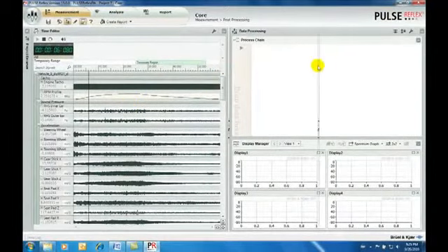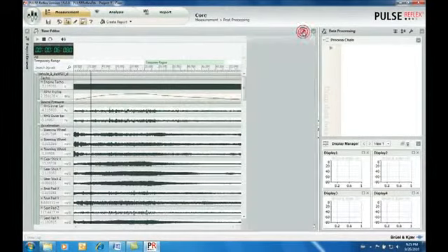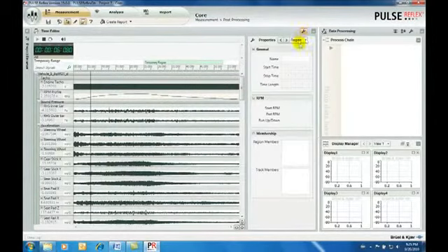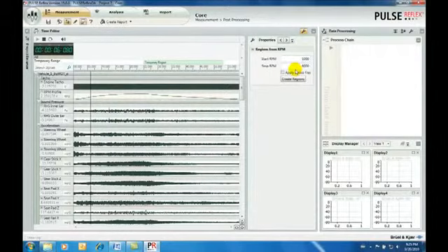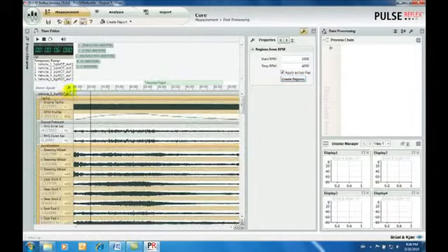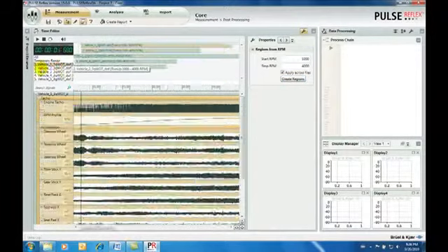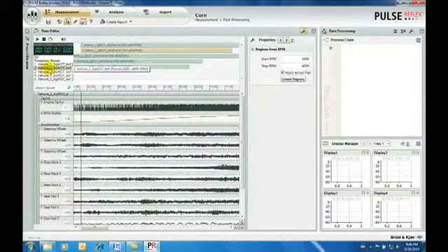We want to perform an analysis of the acceleration data versus engine speed. We have seen that a suitable common speed range would be around 1000 to 4000 RPM, so we enter these as our limits for creating time regions. With a single click of the mouse, all 5 run-ups are selected. We take a final quick look at the individual run-ups before selecting all of them for analysis.